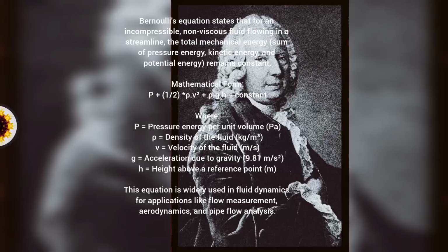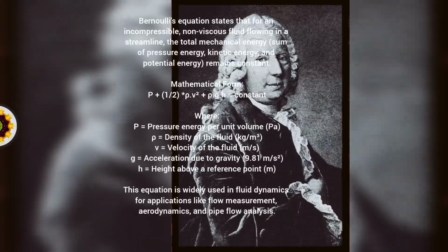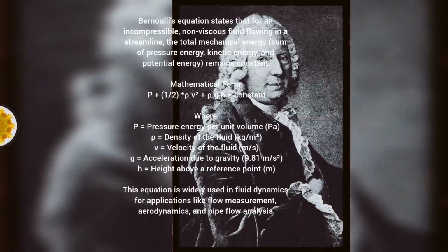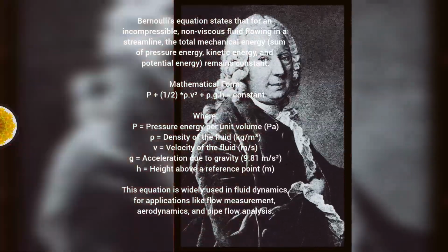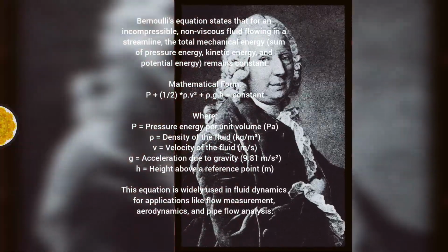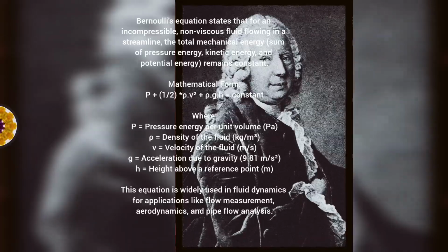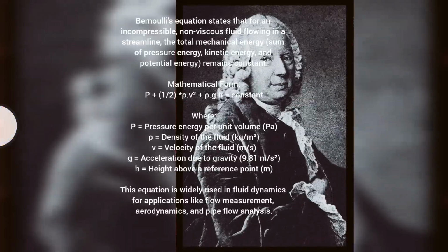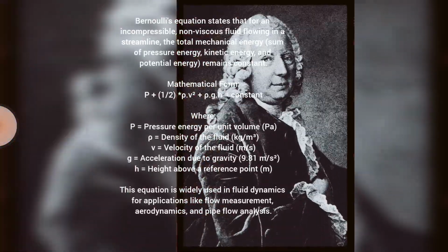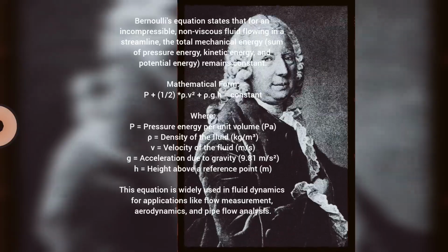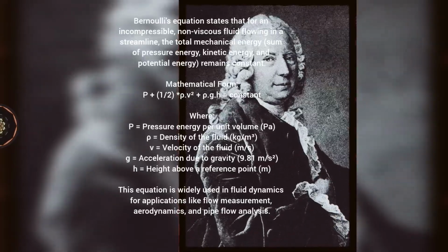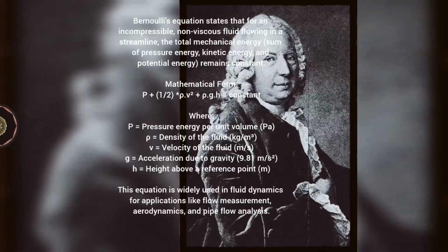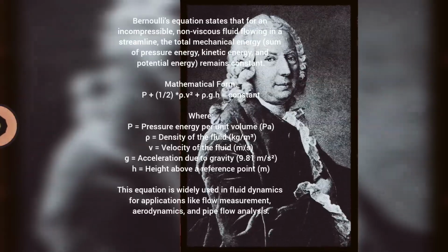You got it. For those situations, you need more powerful tools, like the Navier-Stokes equations. Speaking of Navier-Stokes, the candidate said those are way more complex. What makes them so different from Bernoulli? Well, for one thing, Navier-Stokes deals with viscosity head-on. Remember those sticky honey molecules. It factors in all that friction. So unlike Bernoulli, which pretends friction doesn't exist, Navier-Stokes embraces the mess. Exactly. And it includes other forces, too, stuff Bernoulli ignores.